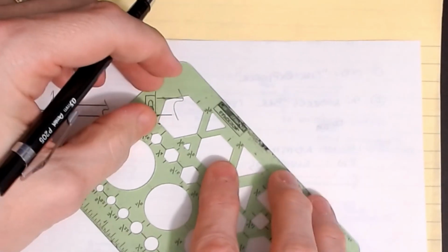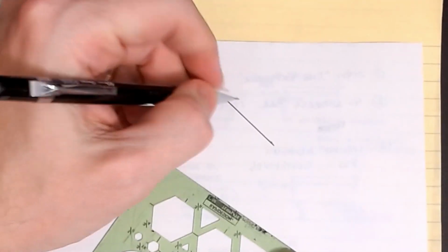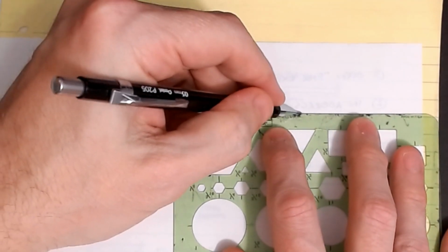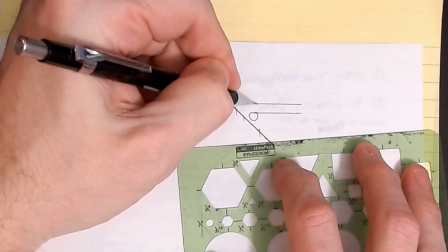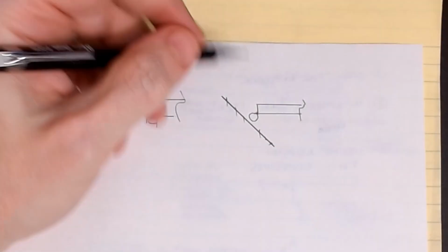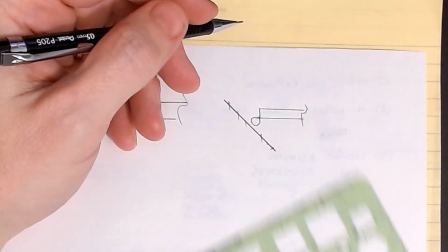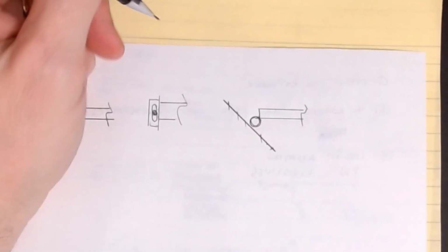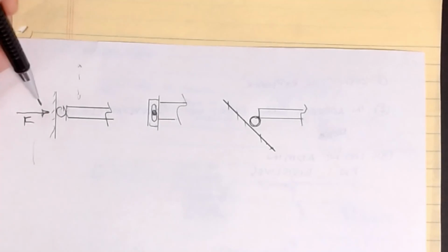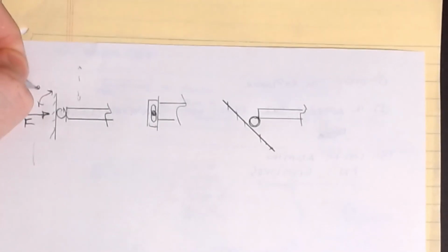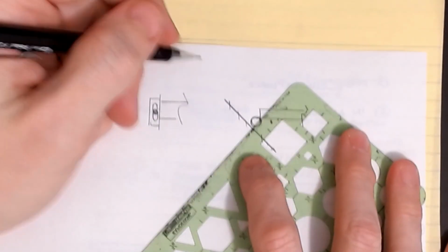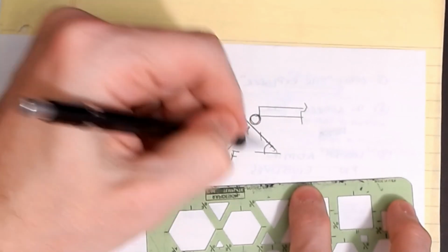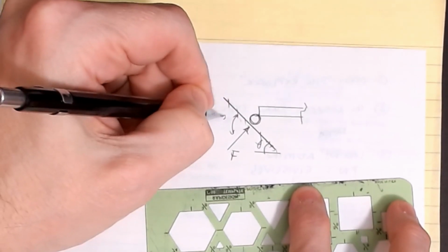All right, the other one we want to look at is what happens if we have a ramp and a roller is happening here. So here's my roller, and now let's just say that the member is horizontal. It could be vertical, it could be anything. Let's clean that circle up a little bit. Okay, a little better. The reaction that shows up on this, again, the definition is that this is 90 degrees. So this one would be in this direction, F, and if this is some angle theta, that's 90 degrees off of that theta.